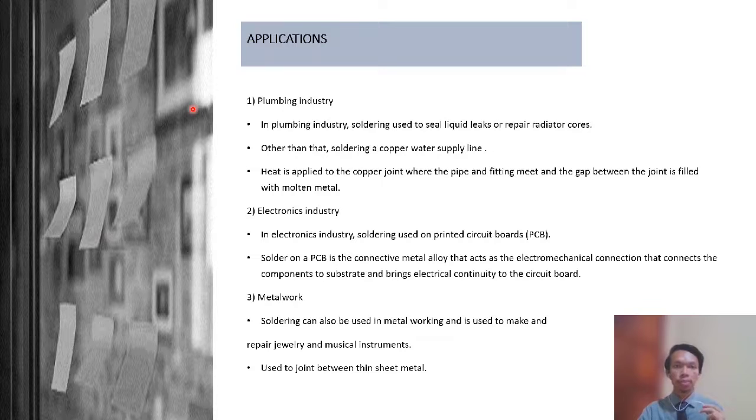And the next point is applications. For the plumbing industry, soldering is used to seal liquid leaks or repair radiator cores. Next, soldering a copper water supply line, and also to join the pipe and fitting, in order that the gap between the joint is filled with molten metal.